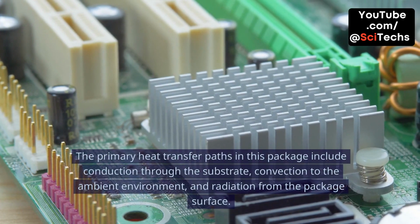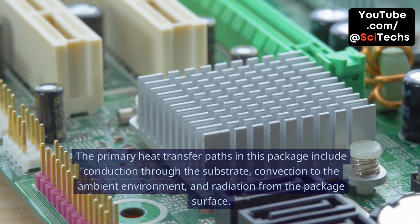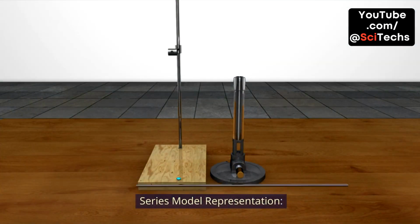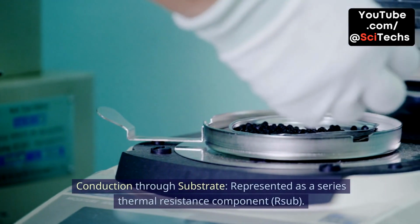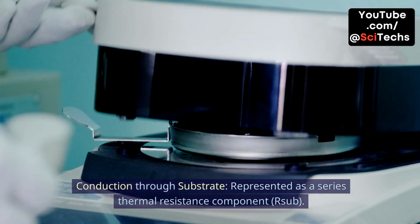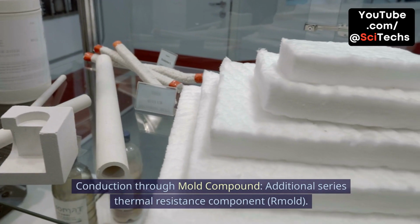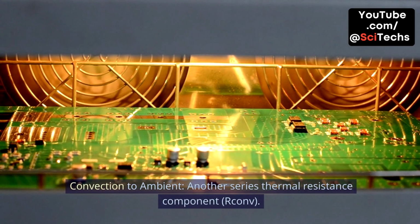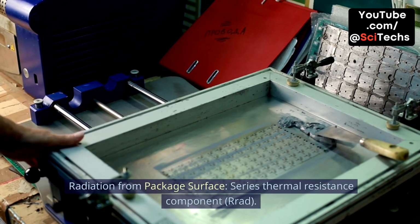The primary heat transfer paths in this package include conduction through the substrate, convection to the ambient environment, and radiation from the package surface. Series model representation. Conduction through substrate, represented as a series thermal resistance component, R sub. Conduction through mold compound, additional series thermal resistance component, R mold. Convection to ambient, another series thermal resistance component, R conv. Radiation from package surface, series thermal resistance component, R rad.